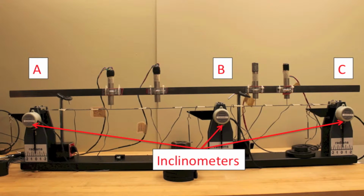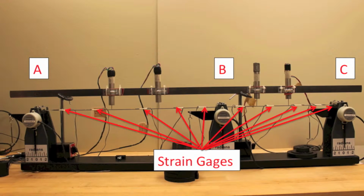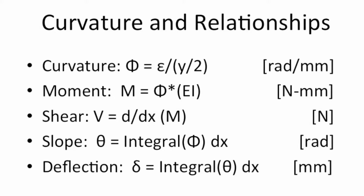Inclinometers have been installed at each support to give values for the slope of the beam at those locations. 5 strain gauges have been installed on each span, which allow us to find the curvatures at those locations. Subsequently, the bending moment, shear, slope, and deflection diagrams will be calculated from this information. The relationships we are interested in are displayed here. Curvature, moment, shear, slope, and deflection can all be calculated once we have the strain measurements.